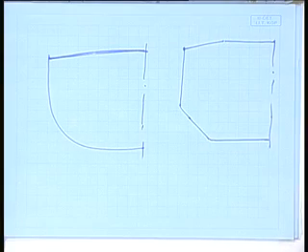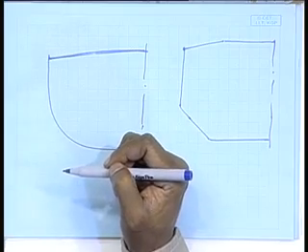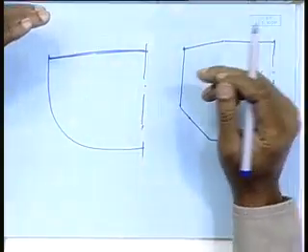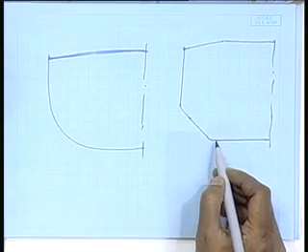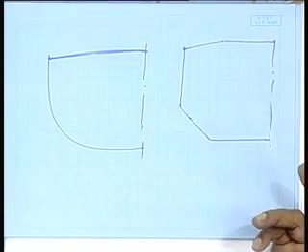This is the difference. That means I give a well-rounded bilge. The moment I give a well-rounded bilge, the forward part becomes double curved, the aft part also becomes double curved, or I can give a chine, double chine. So the entire thing remains in the chine construction. So there is no bending of plates involved.